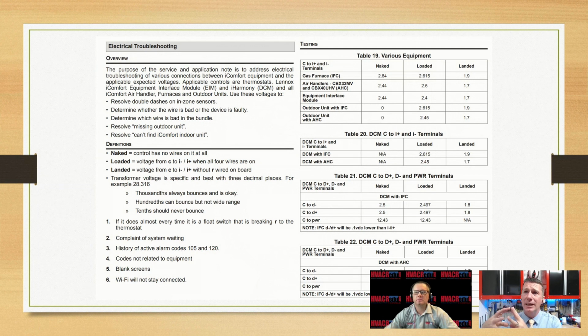Yeah, I'm not putting a lot of current through it. So I'm actually communicating. It is very sensitive. So if I have oxidation, cuts, nicks, breaks, or splices, oopsies. If you're on a communicating system and there's an existing splice in your control wire, the very first thing you do is run new wire.